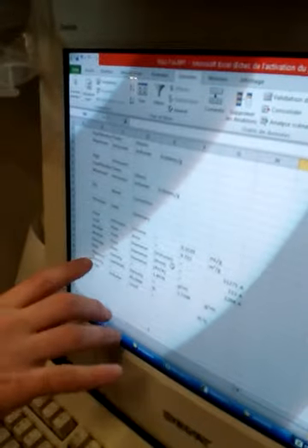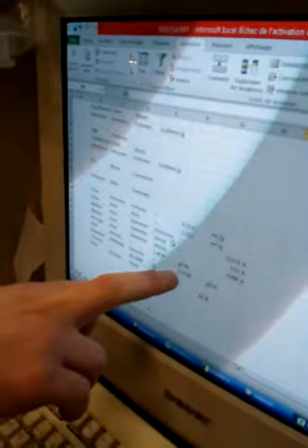And here it's the bulk density, so the volume density, and it's 1.4. And maybe if we reanalyze the real apparent density, the real specific gravity with the pycnometer, we could have a better estimation of porosity,